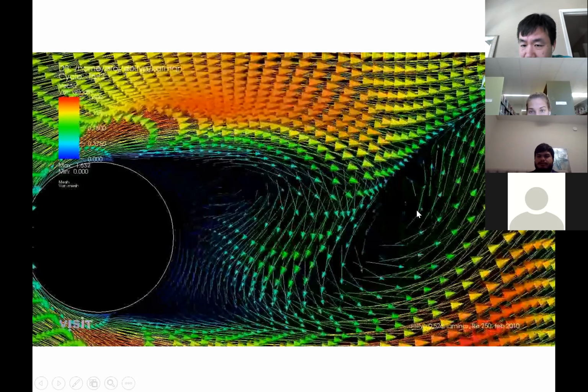At every point, you have an arrow coming out, which means that at every point, Fluent calculates a velocity for you. So you can realize that velocity into magnitude, the length of the arrow, and the direction of the arrow. So you have thousands of points. You put them together, use the vector field, and you can actually show the flow field.